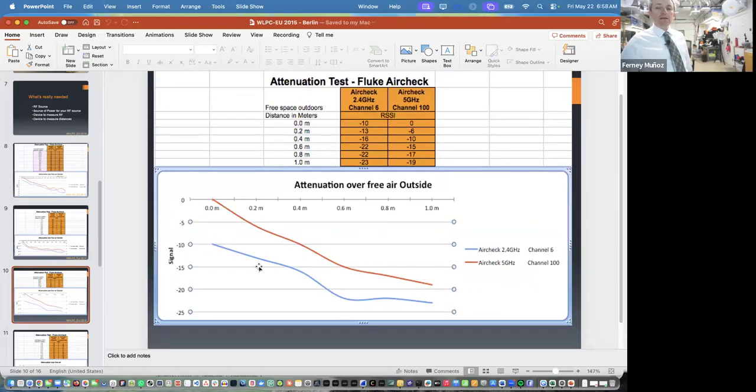And then I said, okay, let's just look at the very first meter. Notice the drastic changes in signal loss, the energy that is lost in that first meter. I lost 13 dBs in here, went from minus 10 to minus 23. That's 13, well, 10 plus 3, that's 20. So I lost 20 times the energy in here.